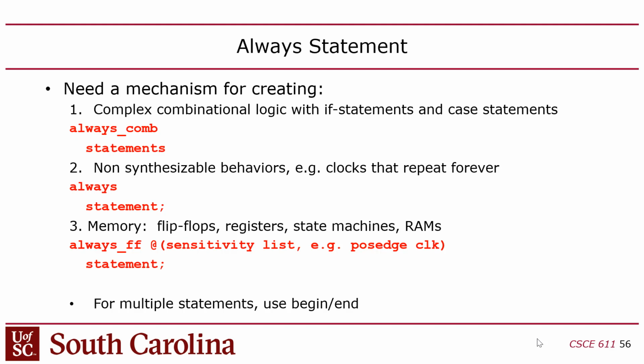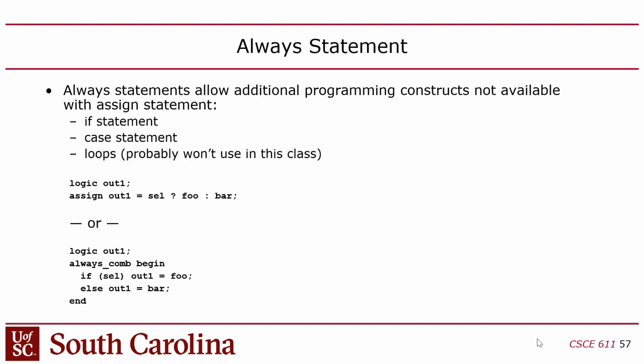However, there's always just the always, which does anything, but you can get yourself into trouble if you use always, because adding these little suffixes gives you some protection. It allows you to tell the compiler exactly what you're trying to do in that always, okay? So I know that's a little vague, so let me show some examples here.